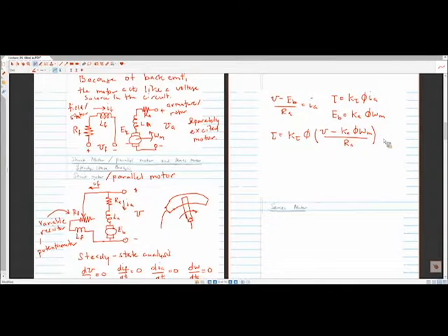And oftentimes, if you look at spec sheets of motors, you'll see stall torque. That's a very common specification. That's telling you how strong the motor is when it's at 0 speed. So it's a good metric to say, can you start something? Is the mechanical load on the system so strong in terms of torque that I can or can't have the motor moving, which is important if you ever want to get the system started?